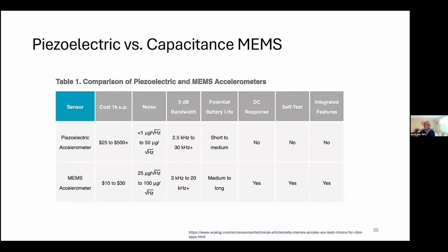So why should this matter for sleep activity? Well, there are two important differences in the way acceleration data is generated and formatted. First is the piezoelectric material only responds to changing stress. So they cannot generate a constant signal response to steady forces like gravity. As a result of that, there's no DC response, while the MEMS accelerometer does.